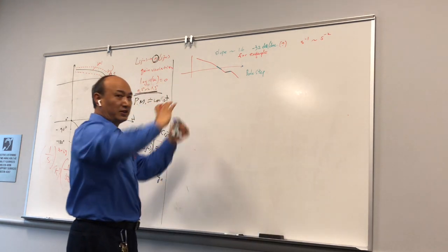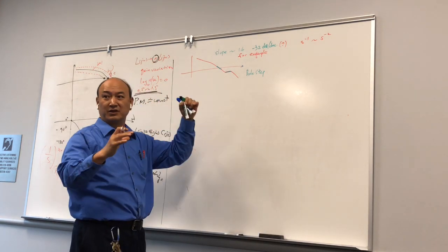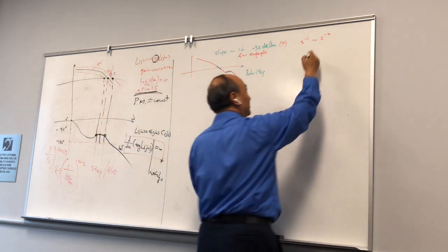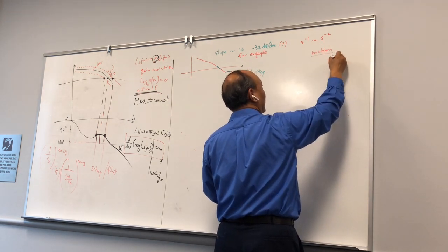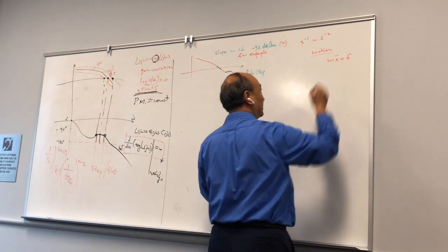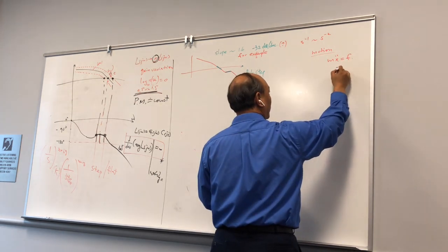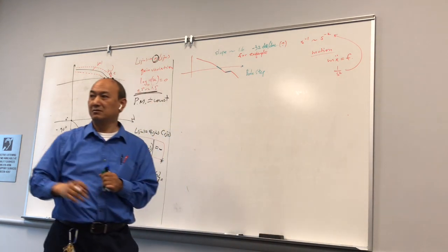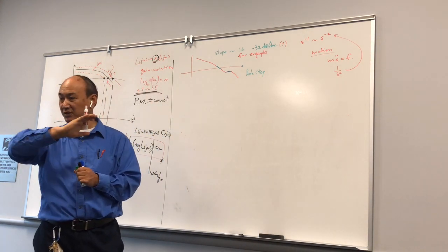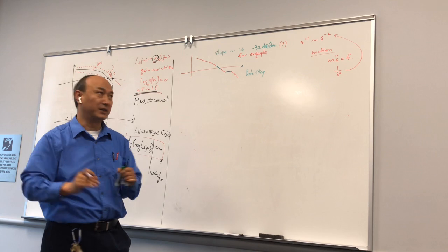So the single integrator versus the double integrator. In a motion system, you have m x double dot equals f, right? So this is 1 over s squared, so it's this one. So a motion system is minus 40 dB per decade.